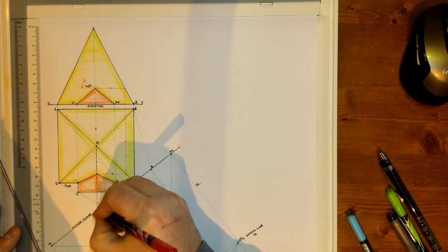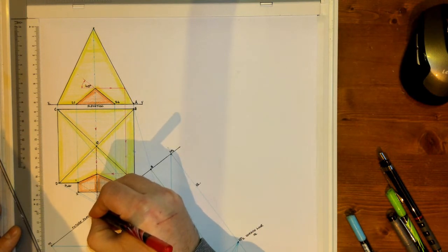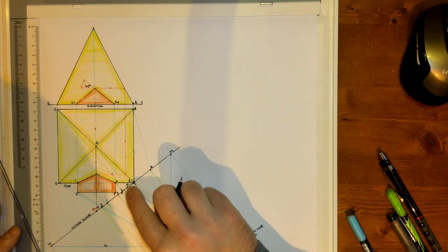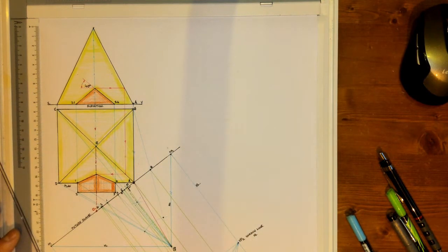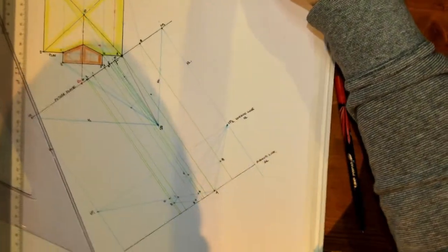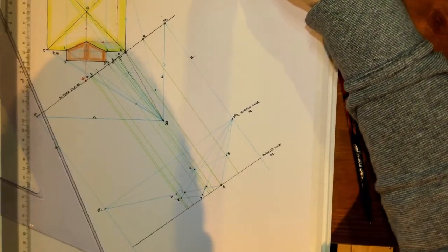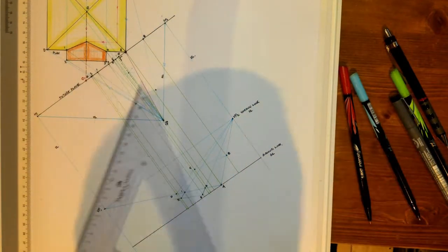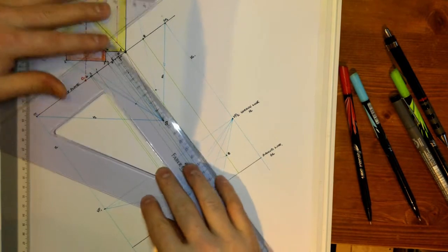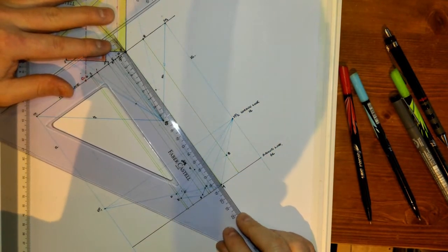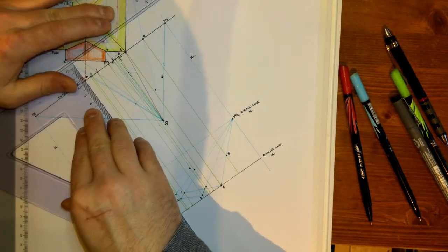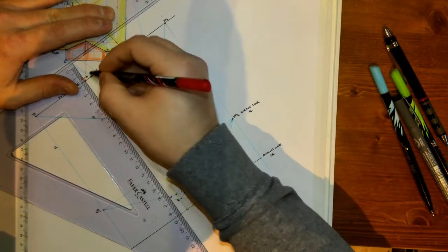Now, we're going to call this O1, because I don't want you to confuse it with O where it actually is when we get the elevation itself. What we're going to do with this O1 line is project that down now at the same angle as the rest of the lines. So, again, I'm going to line up with that line for A. I'm going to slide it over to O1, and I'm going to bring that line O1 down.